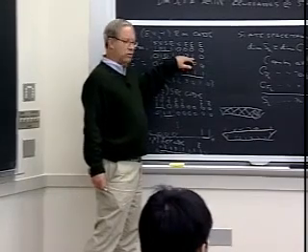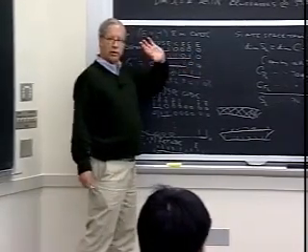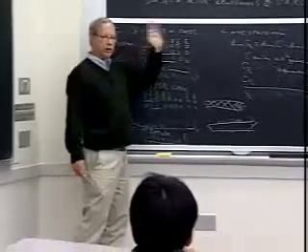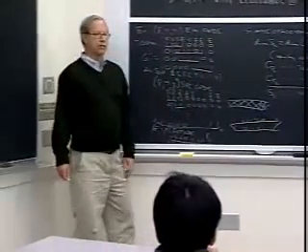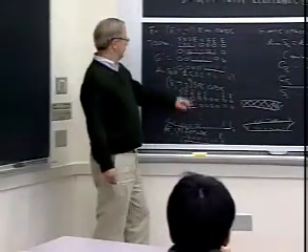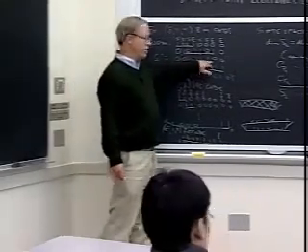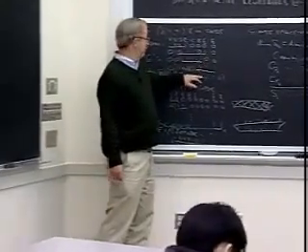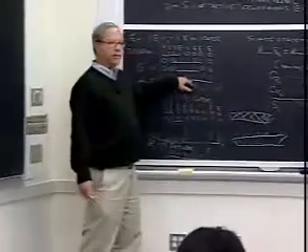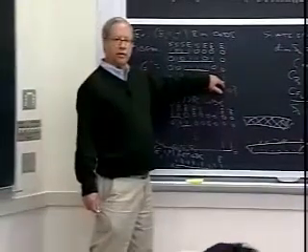So you need to save U2 for 5 more times, and then it disappears. We don't need to save it anymore. We can let it drop off the end of the shift register if you like. U3 comes in at time 3, and this is its impulse response. And U4 comes in at time 5, and this is its impulse response.